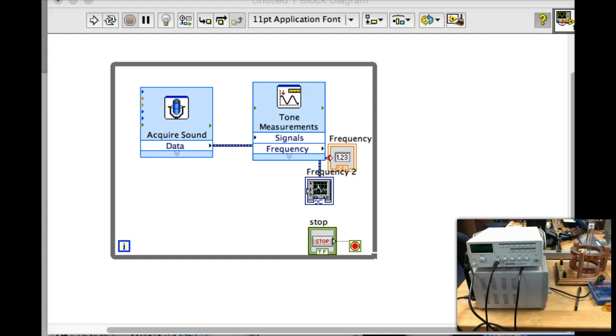Because you are only able to get data from your Arduino card into your computer so fast, okay? And when you get into LabVIEW, that's the thing that's actually adding the timestamp for you, okay? So that means your Nyquist frequency is going to be super low, okay? So did you get to a place where the frequency is accurate up to a maximum value, and then it goes lower again, right?